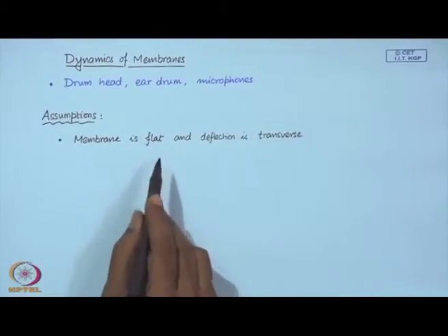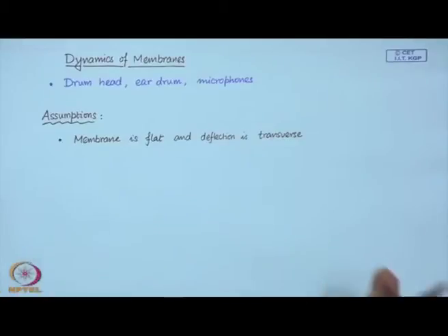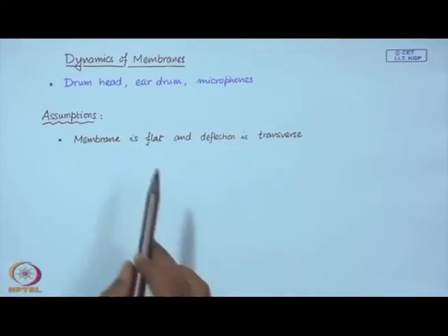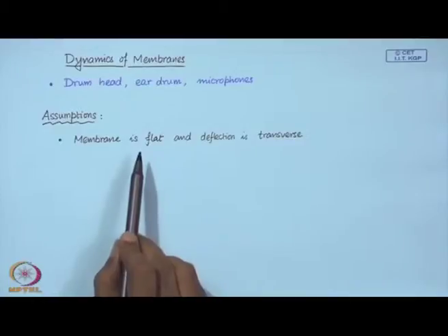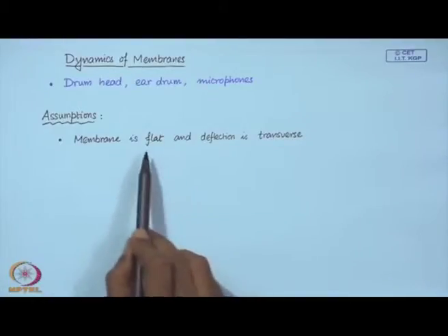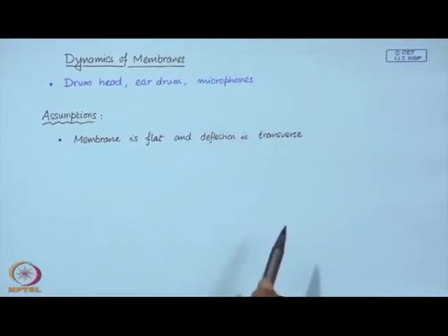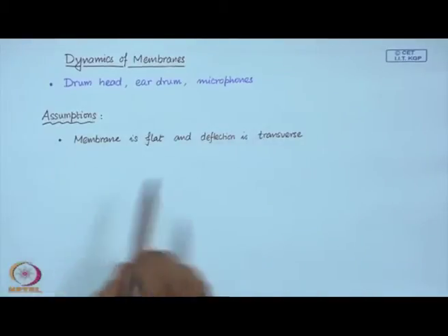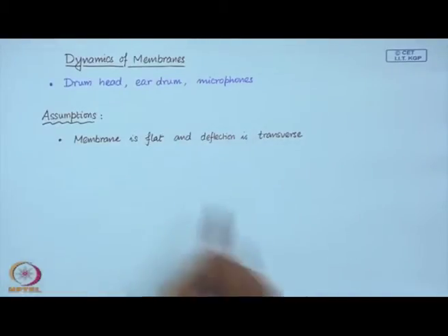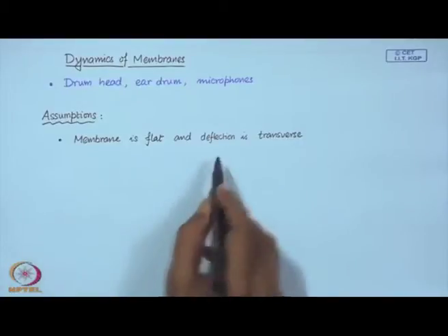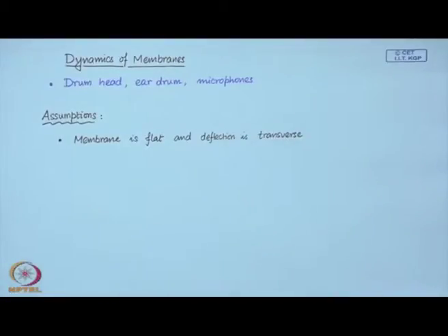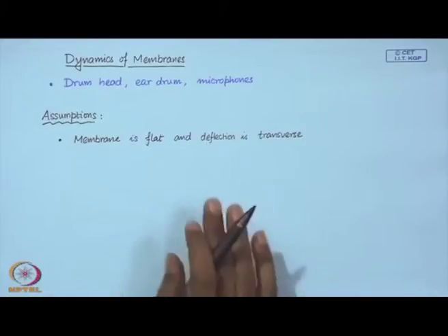When you have, let us say, an inflated membrane, like a balloon, the dynamics is more complicated, because the deflection can no longer be considered to be just transverse. There is a coupling between the transverse and the in plane modes. So, we are going to assume that our membrane is flat, so that we only have to consider the transverse deflection of the membrane.